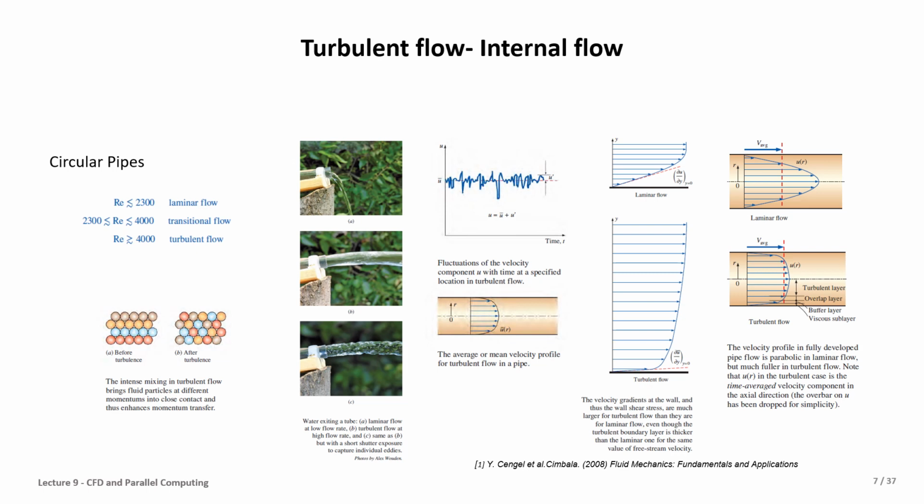Also, when we talk about the boundary layer, when we have the laminar flow on the surface, the slope of the velocity profile is different and it's larger, but for the turbulent flow it's lower, and it has a different slope for these two different regimes.